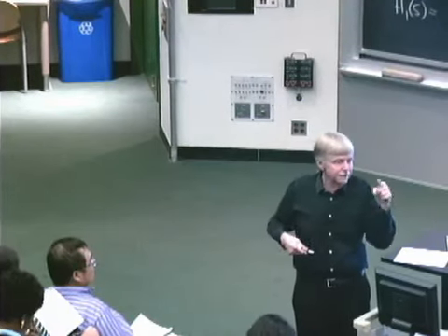What's the furthest? Left is good, right? Left is good, everybody knows that. So right is bad. So small distances in the s-plane correspond to slow responses. Big distances correspond to fast responses. That's what we saw in part 1. So we're trying to push the pole that way as far as we can. How far can we get it to go?